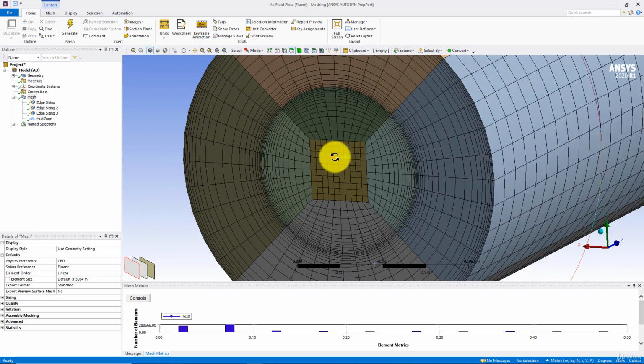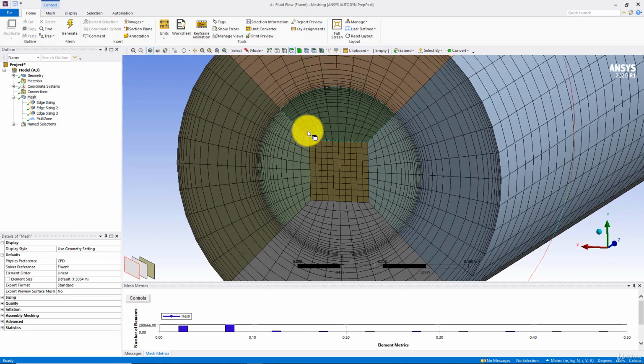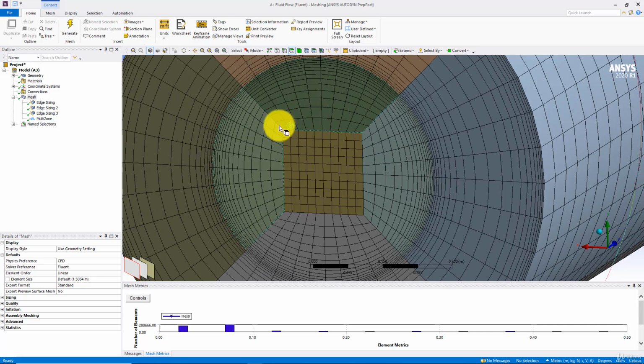And one more thing, just a comment. Right now the mesh is final, but it's just a comment. This region, which you can see here, this square region, either the size of mesh on these edges is too large here, or maybe we have put more sizes on these edges, or maybe this square is very small here. So I will suggest that you increase the number of nodes here so that this size and this size, this square and this square, are matching.